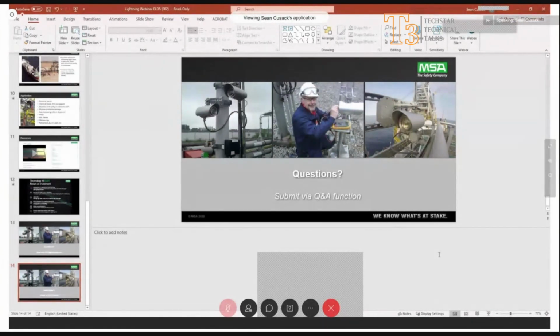Do you suggest using the Modbus for better fault diagnosis? I would say it all depends on where these are going to be mounted. If you're looking at somewhere up high, let's say it's an ammonia rack or something along those lines, and you've mounted them 50 feet away from the ground, you might have trouble Bluetooth connecting to that. And I don't recommend climbing on scaffolding or ladders or anything like that to get to the unit. So that would be probably a good case where the Modbus would be a very good idea. Okay. Sometimes Bluetooth can be finicky.